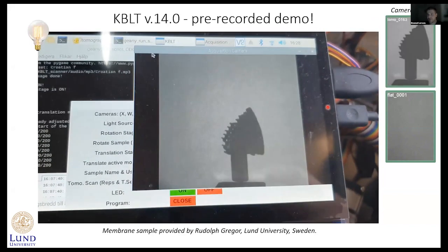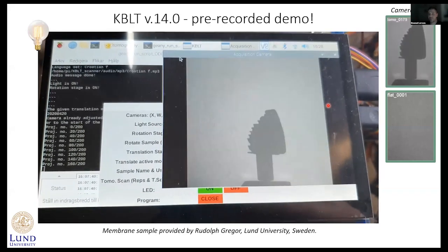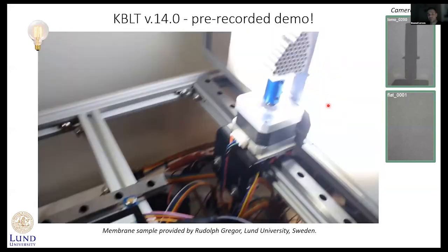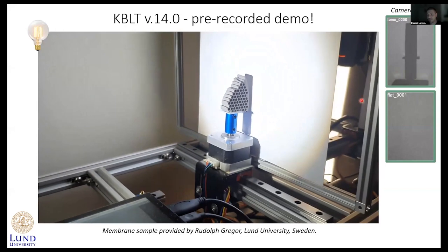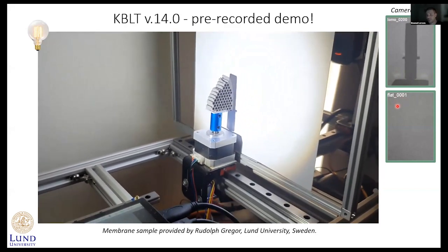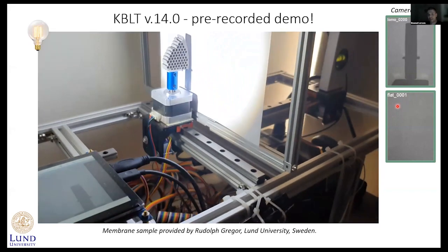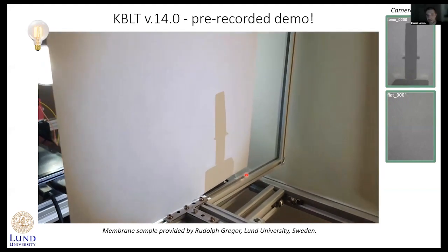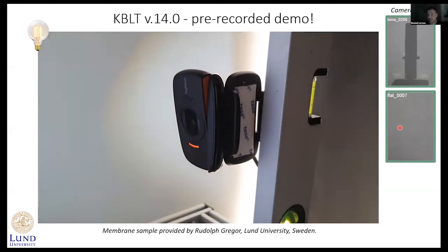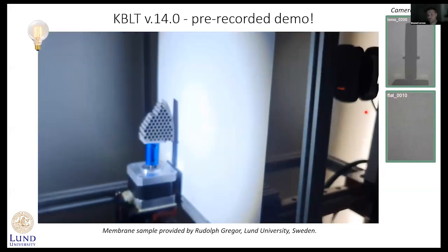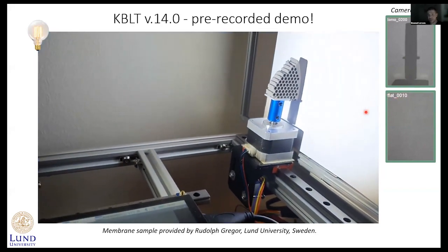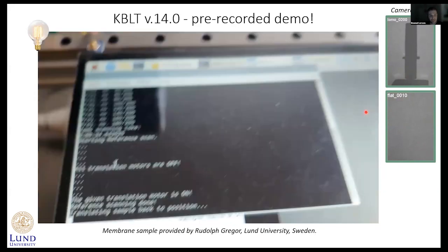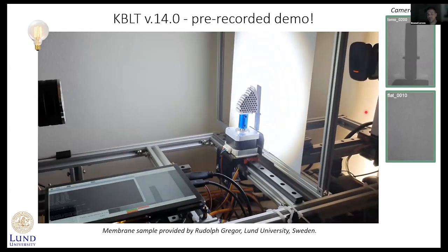and after we have reached 200 projection images, it is time to move the sample outside the field of view, and we capture these so-called flat field images, which is an image of the empty background. This LED light here is just telling us that a motor is moving. Now soon you will see the counter adding up to 10. We take 10 flat fields, so we have a little bit of averaging to do. And now the scan part is done, actually. It took 34 seconds. And now the sample is moving back to the original position.